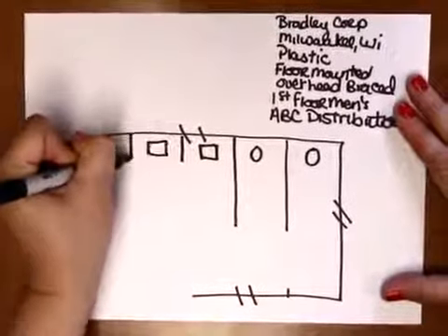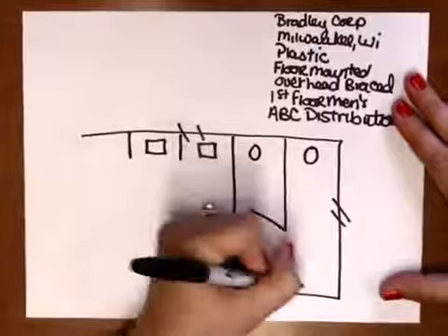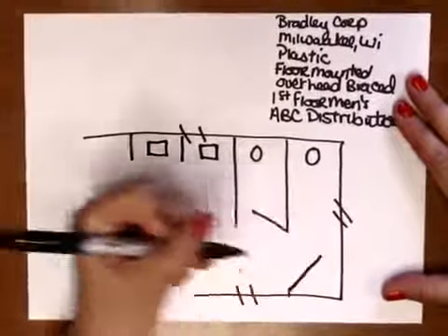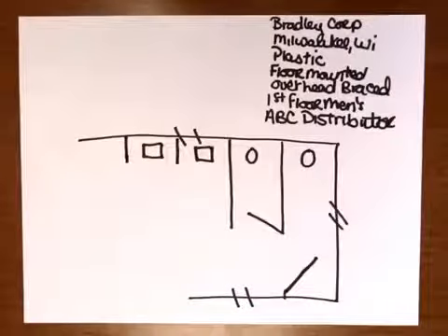For the doors, make sure to indicate if they are hinged on the left or the right side. Also indicate if they swing in or out. In our example, both doors are hinged right and swing in. Okay, our drawing is coming along. Now it's time to add our dimensions.